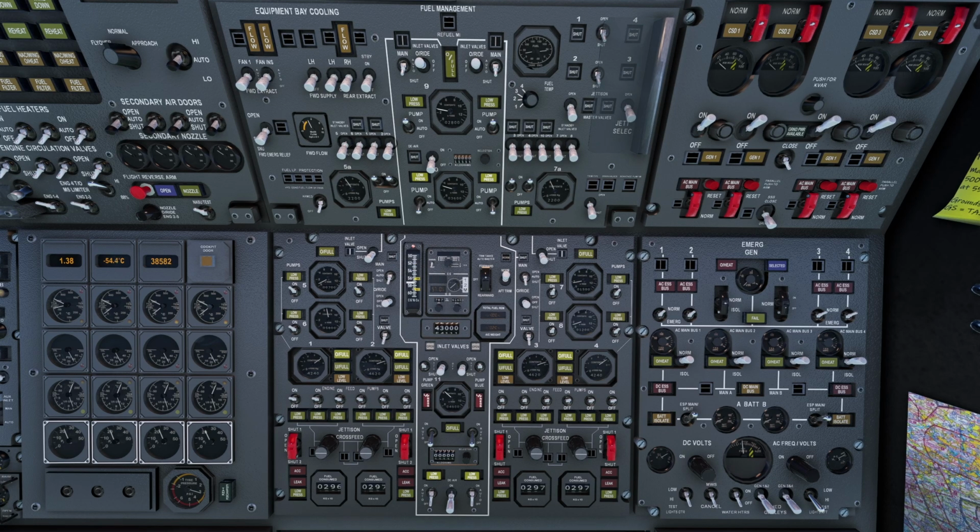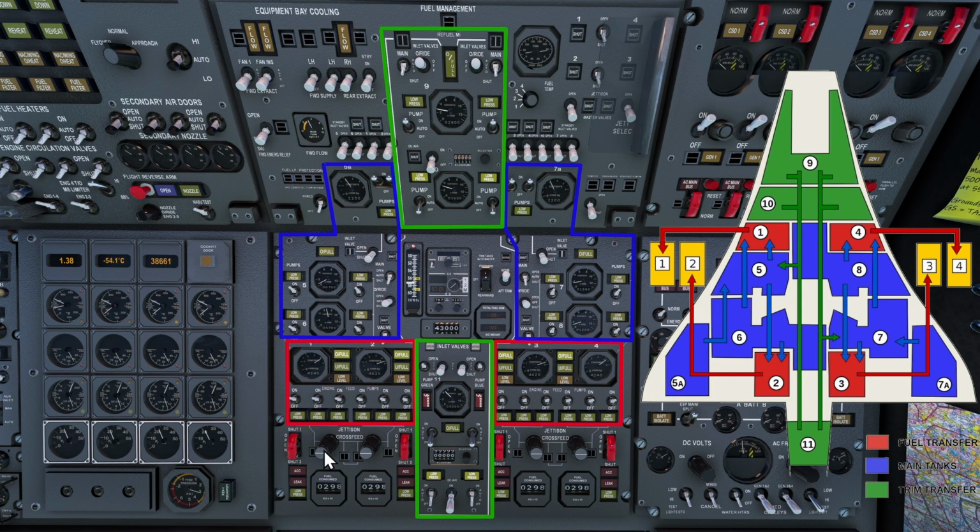Another special tank that we have to take care of soon are tanks 5A and 7A, sorry, which are at the top of the panel here, and they need to be emptied after 1.75 Mach. They're on the outside of the wings to aerodynamically adapt the wings to the supersonic flight. So that we're going to do once we go off afterburners in our climb.